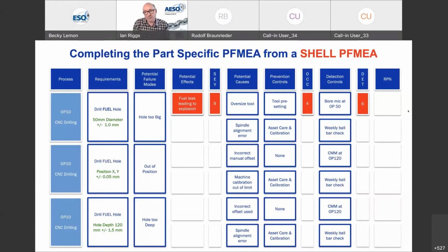And some organizations would work that down the list with the design resource they have, to maximize the use of the design engineer, but also if they do find any severity 1 scores, they know they don't have to do anything else to the right. Okay, but effectively what the team are doing is identifying the effects and then using the scoring criteria to rate the severity, occurrence and detection.